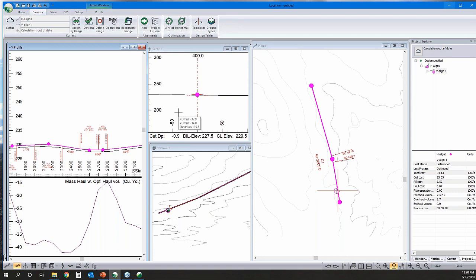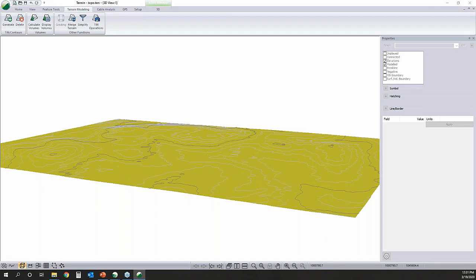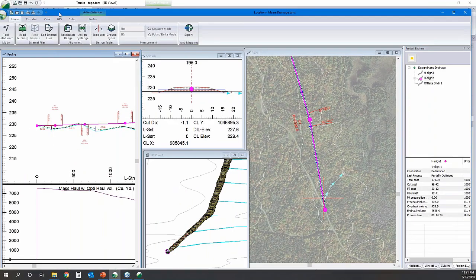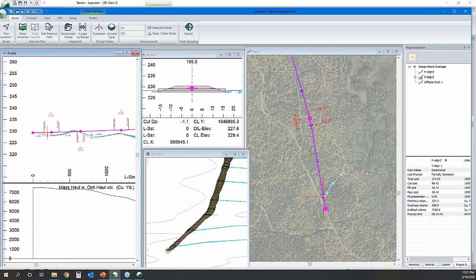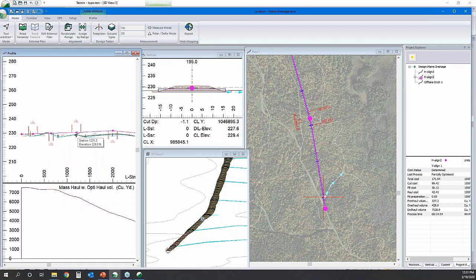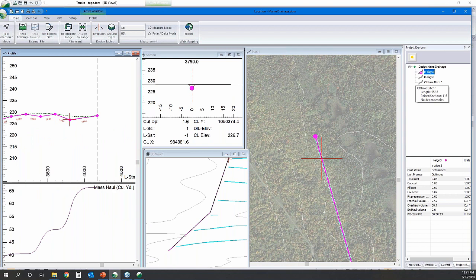So I've kind of taken this a step further in another screen here, and we can just kind of talk about what we've got there. So let's bring this over. So this one, I've got a separate alignment for my ditch. So here this is assumed to be your overland construction where you're end dumping material for creating your prism, so importing all your material and keeping track of where the water's going. So I used one alignment to create my ditch profile. I set it up in the optimizer to do that for me.